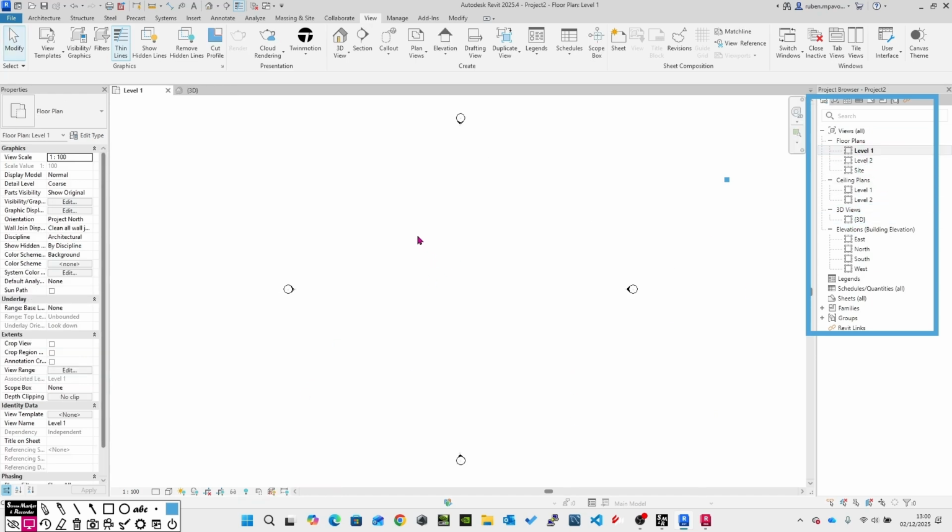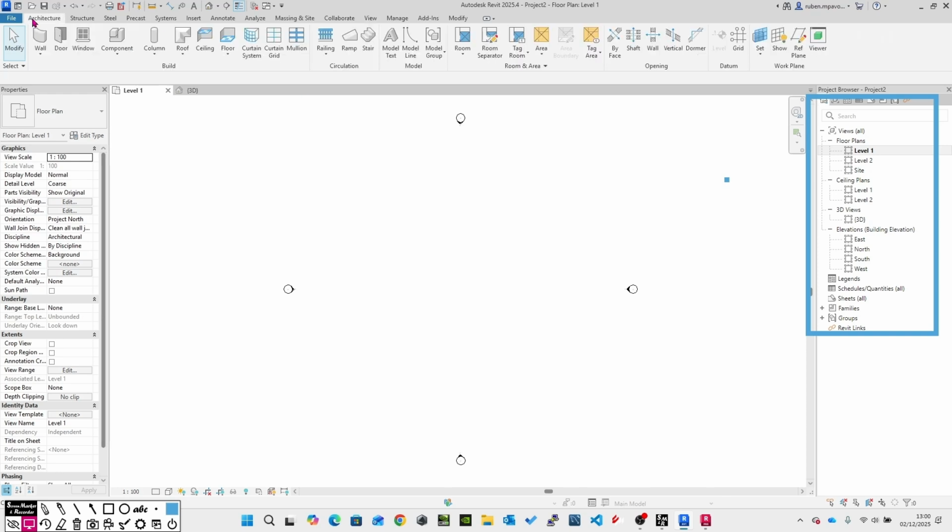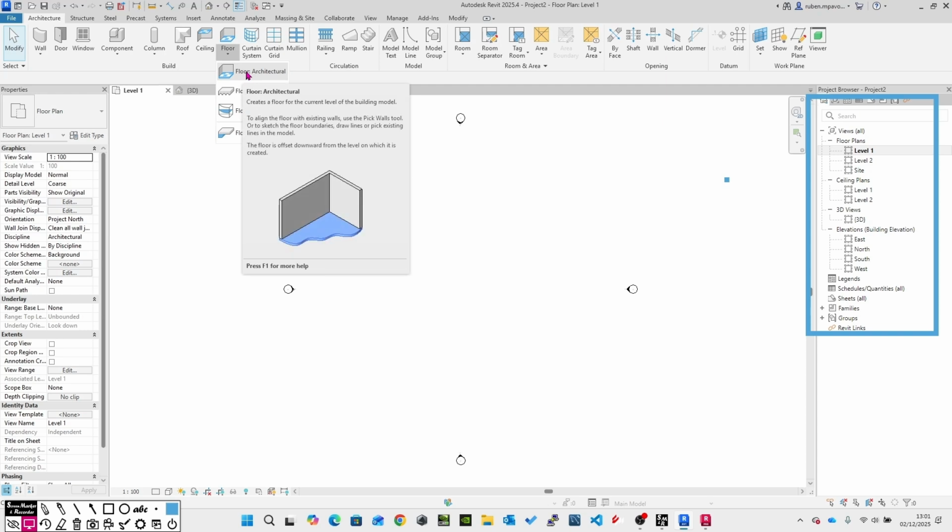So what we are going to do in this video, we are going to see the difference between structural and architectural families. We already know how to create different floors, and we have seen it in the previous video, and now we are going to create it again. So let's go to Architecture and Floor, and we are going to create on the left part an architectural floor, and on the right part the structural floor.